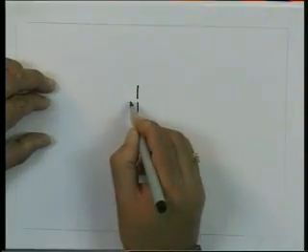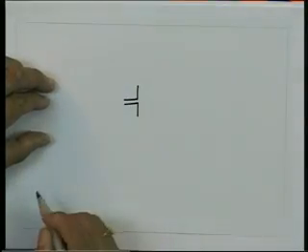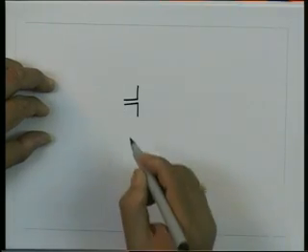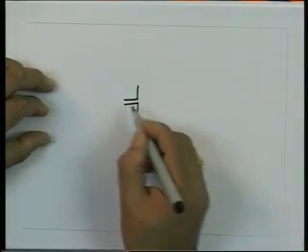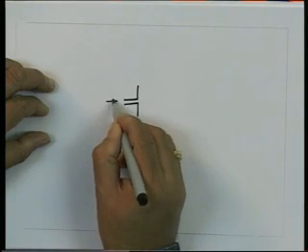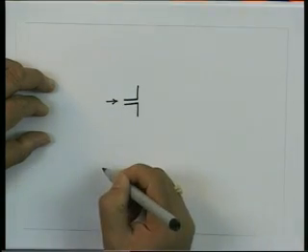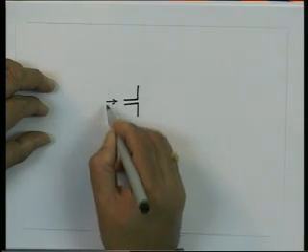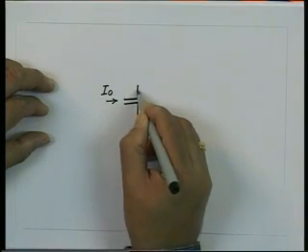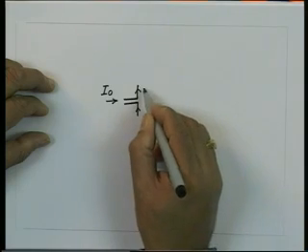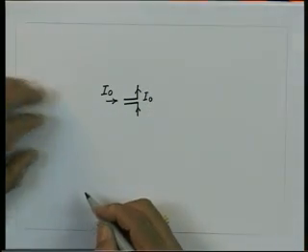Now, if I look at this antenna from the circuit point of view, the Hertz dipole, we can excite this antenna by some voltage source which will give me the current in the terminals. So, let us say if I break the Hertz dipole halfway, so this is my Hertz dipole now, which is broken into two parts, and this is the input through which the current is flowing. So, if this is connected to a circuit, the current I 0 comes like this, it flows through that, from here it comes back. So, you have a current I 0 flowing in the terminals of the antenna.